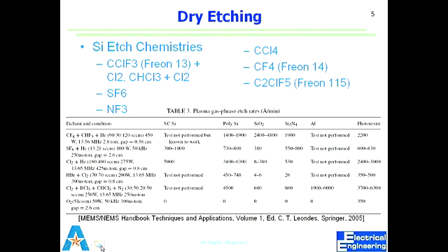So we have to see what we use as the mask material, and we have to know how much of that mask material will be left behind at the end of the etch. Would it be enough to protect this part which is not supposed to be etched? So these recipes are carefully chosen to do the etch that we need to do. This is probably now 7-year-old data.